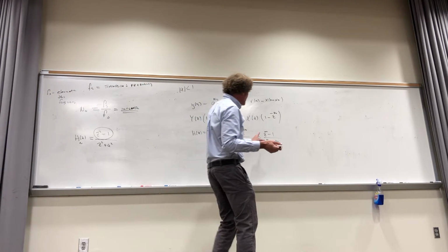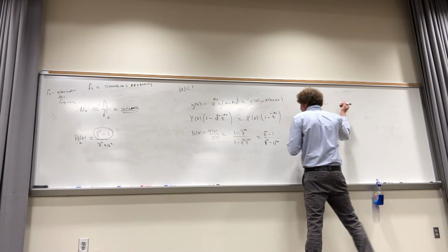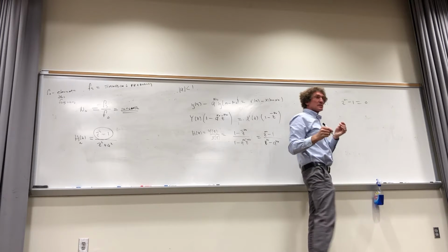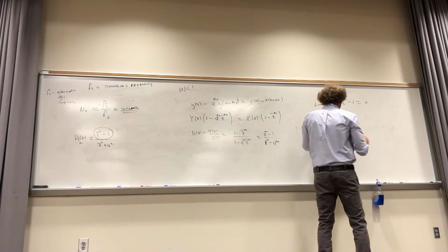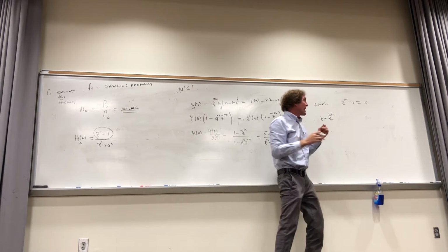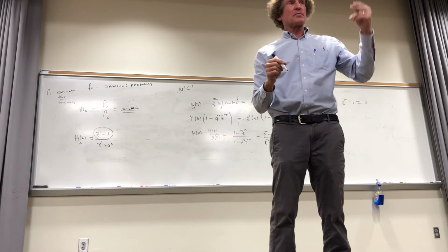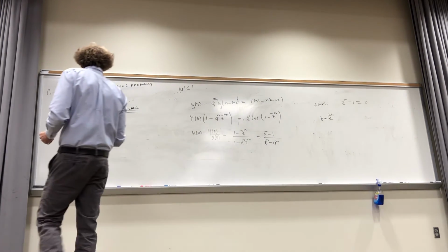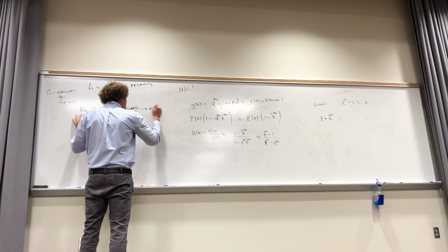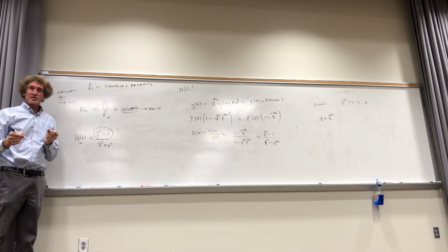Now look here. Where are the zeros for this one? Because we want the zeros. The zeros will be with what? z to the n naught minus 1 equals 0. Correct, class? Now, follow me on this. What is z in terms of a filter? Well, z is e to the j omega, right? Let me just leave it as omega, correct? Now think about this. We're sampling, right? Something I failed to say. This is also the period. Or it's the period of the waveform. It's periodic with n naught when you sample because of this condition.